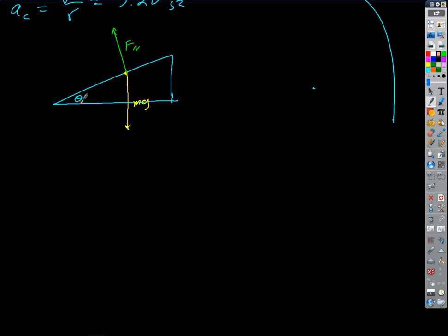That's just inconvenient, right? Plus they're harder to build. They're more prone to erosion, and we don't really want that. It's just weird. You don't see many roads that are extremely banked, right? So we want to make this as small as possible so that the banking angle coupled with our minimal friction is going to be enough to keep the car on the road, right?